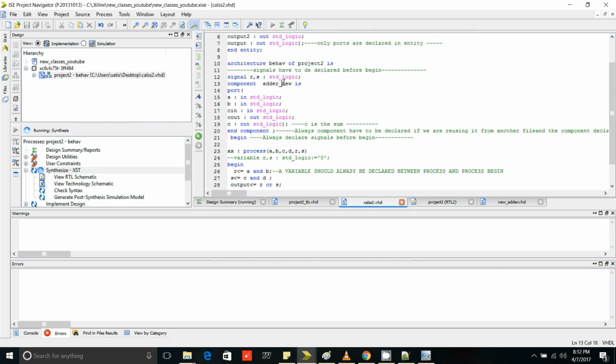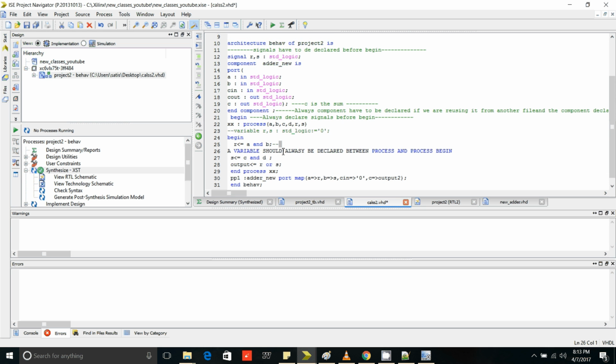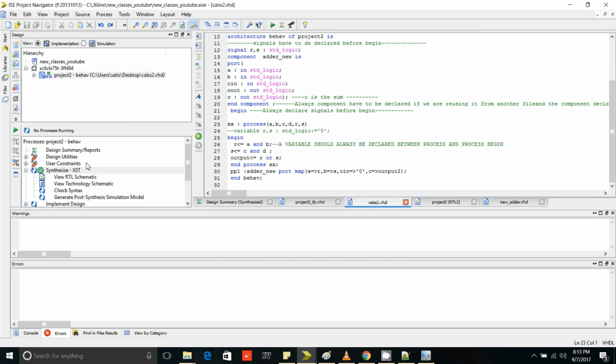It's because once you declare a signal, the signal is common to everything you write in the program. You can use a signal anywhere. If I'm writing another adder or a multiplier, I can use that signal there also. So that's the difference between a signal and a variable. A variable is only defined within a process, and that's the reason why variables should be avoided in VHDL.